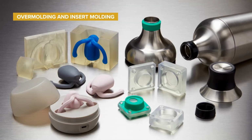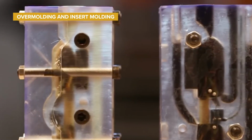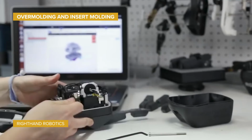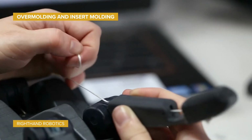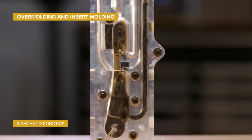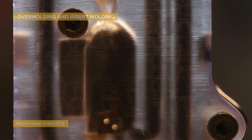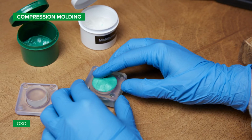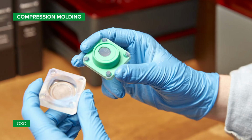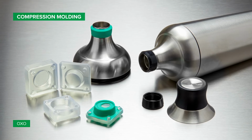3D printed molds can also be employed for molding silicone or rubber parts, and overmolding inserts or internal hardware. Piece-picking robot manufacturer RightHand Robotics brought the production of adaptive flexible fingers in-house with 3D printed molds and overmolding. There is an internal wire channel through the core of the fingers that is only made possible with 3D printing technology. Product developers at kitchen appliance manufacturer OXO use 3D printing for prototyping rubbery components, such as gaskets, by compression molding two-part silicone using 3D printed molds.